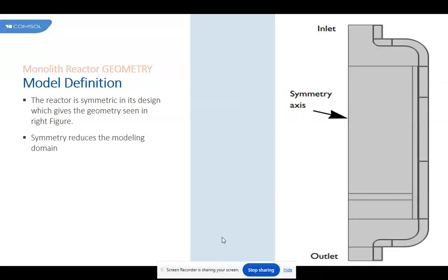Different models are available for calculation of thermal and transport properties: thermodynamic models and kinetic theory. The viscosity of the system is calculated based on the Brokaw model. The thermal conductivity and diffusivity are calculated from kinetic theory and Fuller-Schettler-Giddings respectively. In this model, to simplify the problem, nitrogen is modeled as a solvent. This means that the gas properties are not composition dependent.